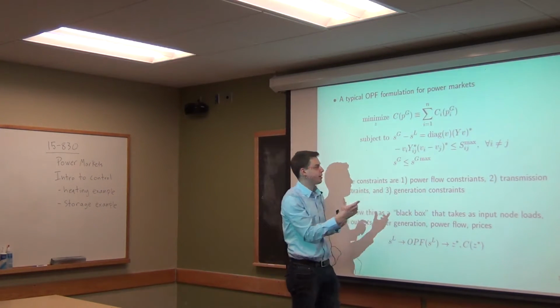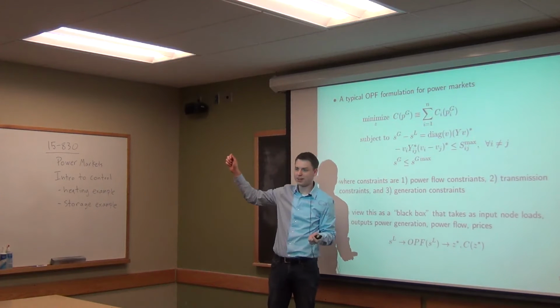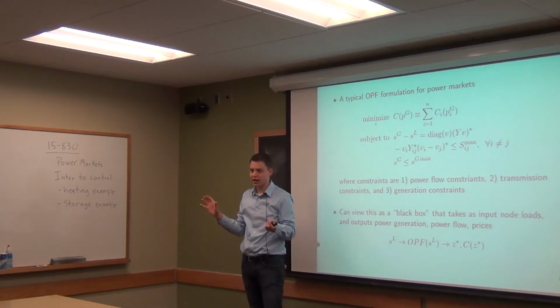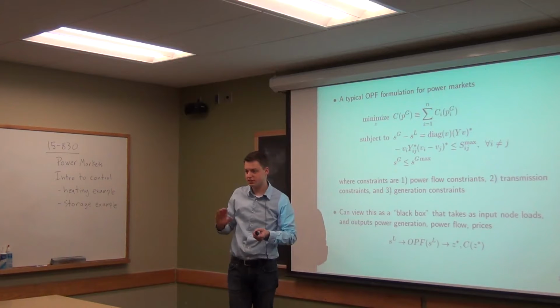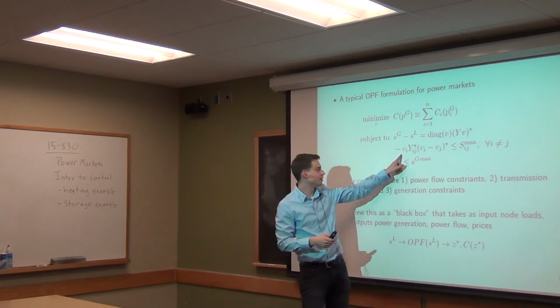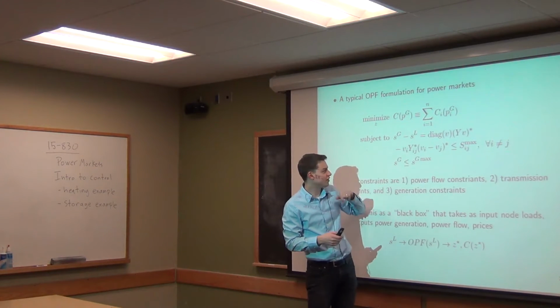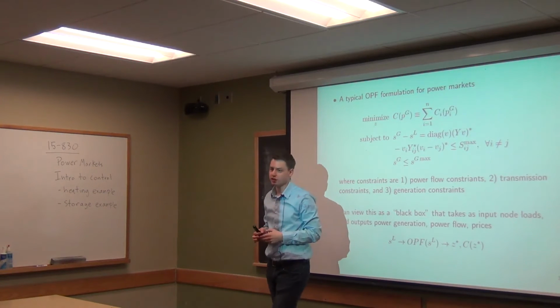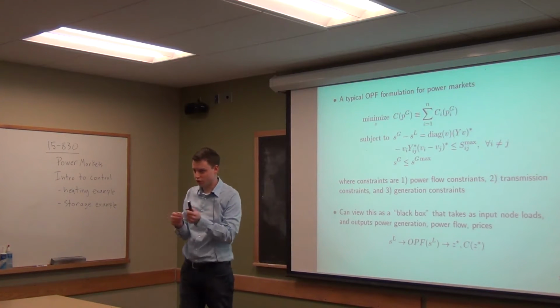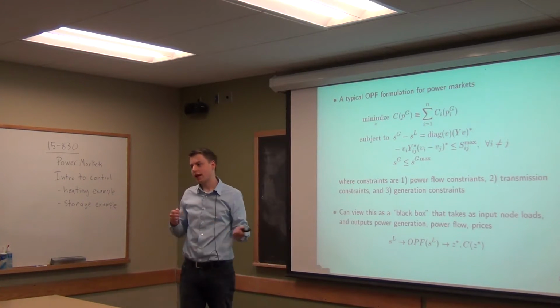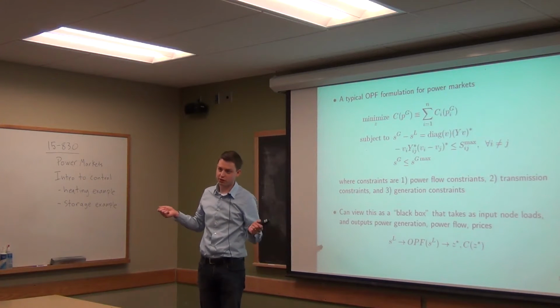It's actually not the same as the power flowing the other way, or the negative power from the other way, because there is loss in the line. So depending how much loss there is, this could actually be different than the reverse there with Vj, but essentially, it's approximately the same, considering those are usually not that far apart. And you typically just constrain the bigger one of these two anyway.